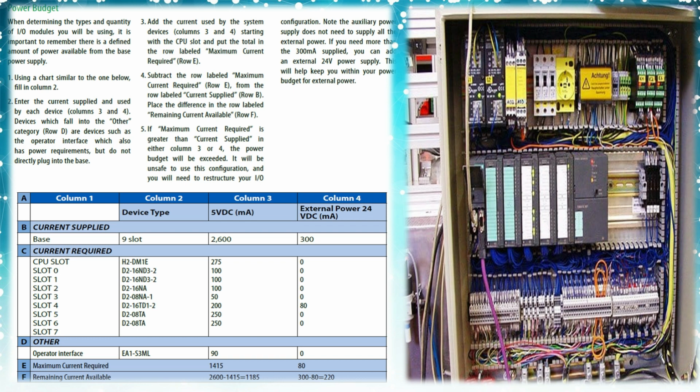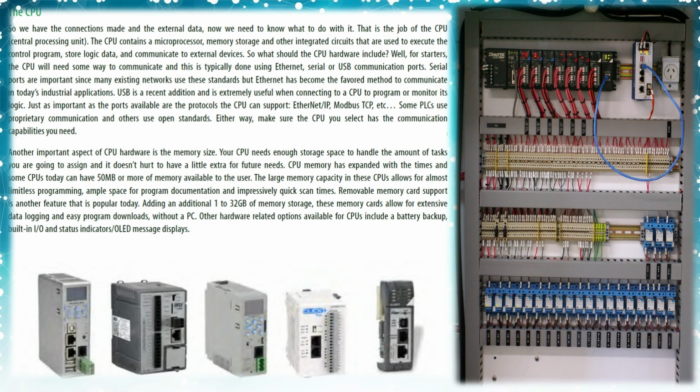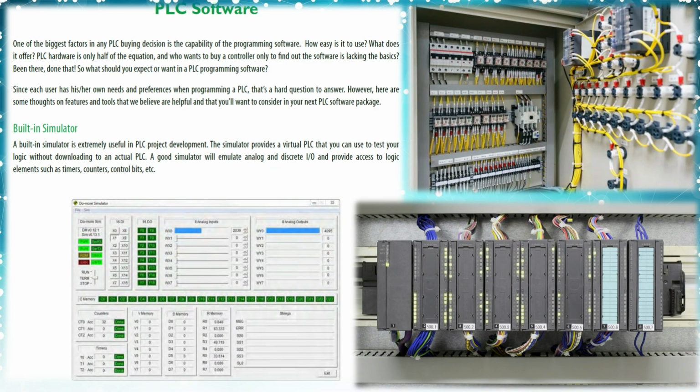In all PLC systems, the PLC rack or chassis forms the most important module and acts as the backbone to the system. PLCs are available in different shapes and sizes. When more complex control systems are involved, it requires larger PLC racks. Power supply module is used to provide the required power to the whole PLC system. It converts the available AC power to DC power, which is required by the CPU and input-output module. PLC generally works on a 24V DC supply. Few PLCs use an isolated power supply.